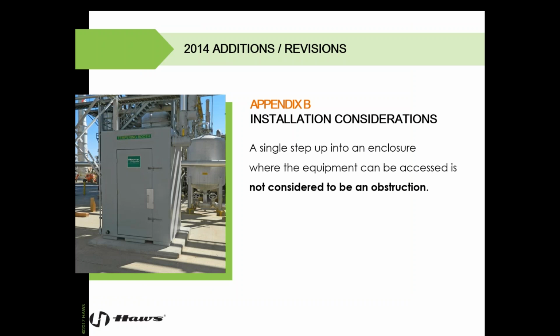One of the last changes in the 2014 revision that's actually pretty important to take into consideration: we added some verbiage around a step up. This is in the appendix, and it's an installation consideration. What it says is a single step up into an enclosure where the equipment can be accessed is not considered an obstruction. In the past, it was.